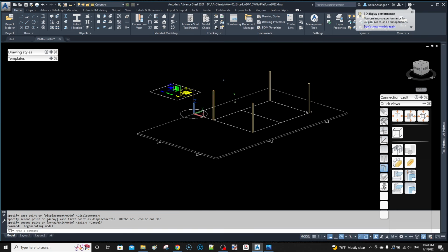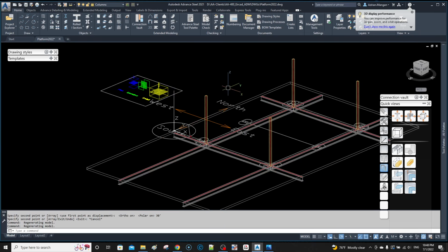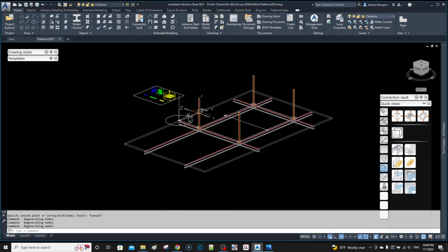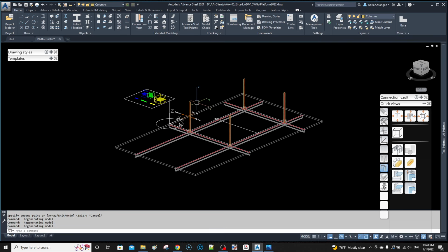The top of the platform is going to be 12 feet. So what I'm going to do is, these columns are going to be a little bit high. So I'm going to put 1.5" grating on top of this. So let's do 1.5" grating. So that means we're going to come down 1.5". So what we'll do is let's draw in the beams.